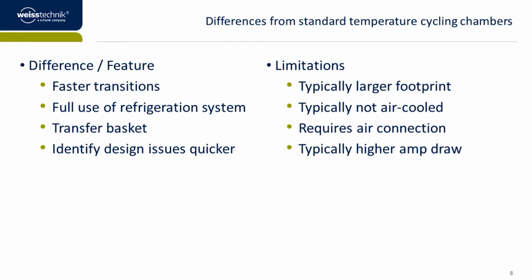Again, when I was referencing, the coil is soaked out, we're able to use the refrigeration system to its maximum potential in just conditioning the product. So it's a very efficient use of the refrigeration and heating systems. But the limitation on that is we typically would not recommend that a larger thermal shock be air-cooled. Because that refrigeration system is running at full steam, we need a more reliable heat transfer method, and we typically wouldn't recommend air-cooled. We would recommend water-cooled for our condensers, just so the refrigeration system can run as efficiently as possible.